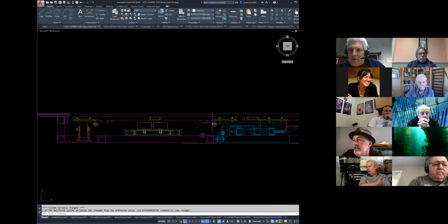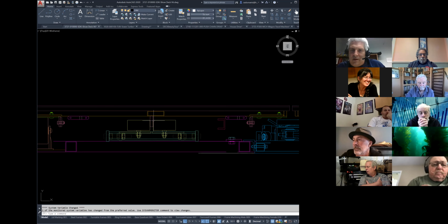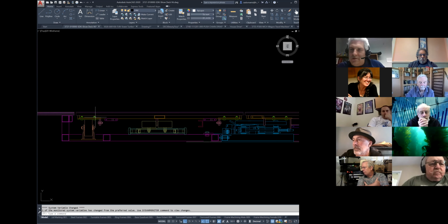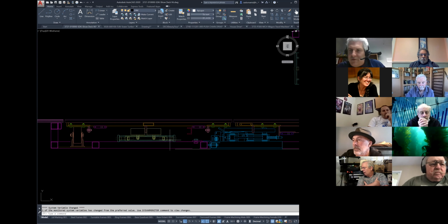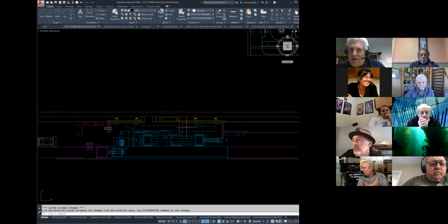And then our platform, our actual donut piece platforms, are these fairly thinly framed segments that wrap around. We have a rolled steel fin on the bottom of those that is located by some guide wheels. That's what keeps the donut running true to the circle. So we have 4 of these around the perimeter, on the quadrants, to locate. And then we are driving both that donut, not shown in this view, but the turntable as well.